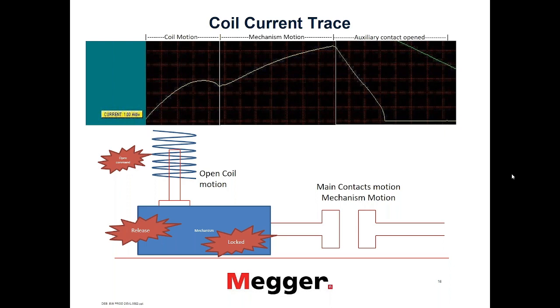While the first trip test, you have to do the test while it's online, especially if you want to do the timing test at least, since you cannot get the current in the CTs without having an actual current going through the CT itself.